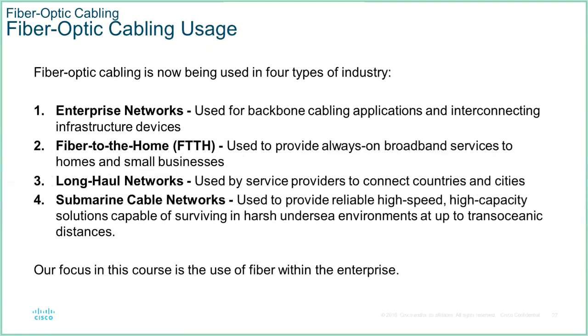In regards to the amount of bandwidth that we effectively can push down through it, Brock, single mode is slower than multi-mode. The trade-off is we get kilometres of distance, like 2 kilometres plus with a single mode strand, compared to 500 metres with multi-mode. So if we've got a long distance to go, we use single mode fibre to get the distance, but the distance comes with the cost of not having as much bandwidth.